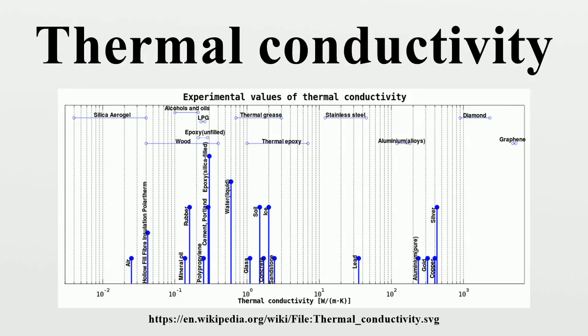Thermal anisotropy. Some substances, such as non-cubic crystals, can exhibit different thermal conductivities along different crystal axes, due to differences in phonon coupling along a given crystal axis. Sapphire is a notable example of variable thermal conductivity based on orientation and temperature, with 35 W/(m·K) along the C-axis and 32 W/(m·K) along the A-axis. Wood generally conducts better along the grain than across it. When anisotropy is present, the direction of heat flow may not be exactly the same as the direction of the thermal gradient.